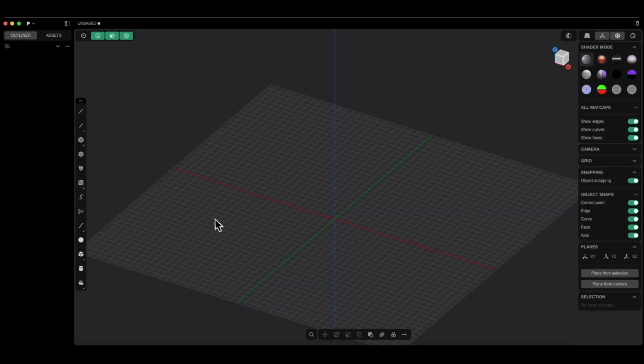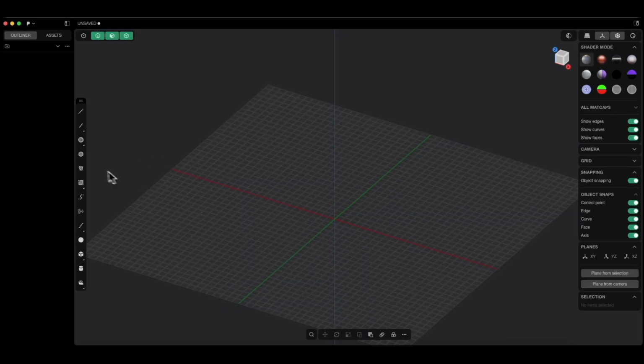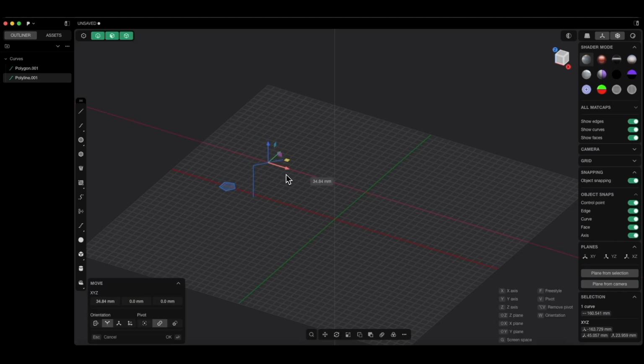Let's go back for a moment to the sweep operation. As you have already seen, this operation works in such a way that we have a profile, and let's create a path here. This path can be in almost any location. That's why I will move this path a bit to this side. The path doesn't have to touch the profile.